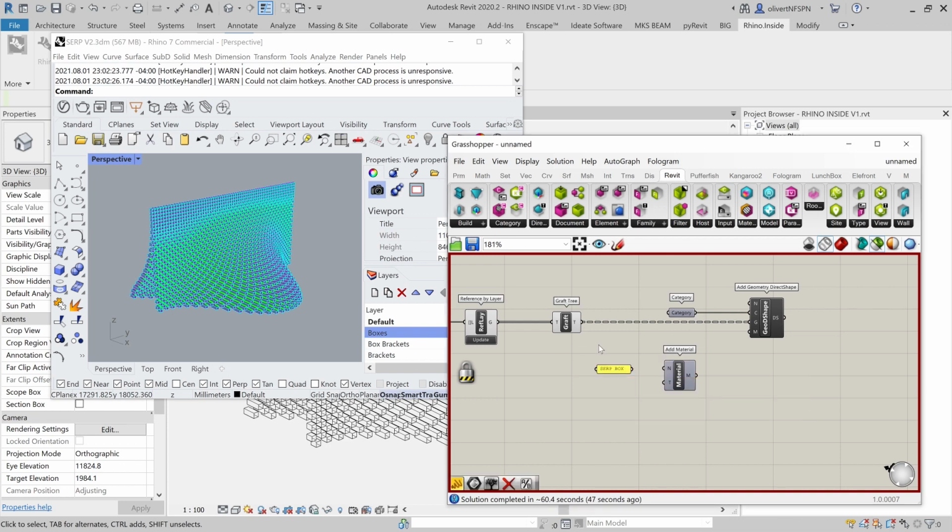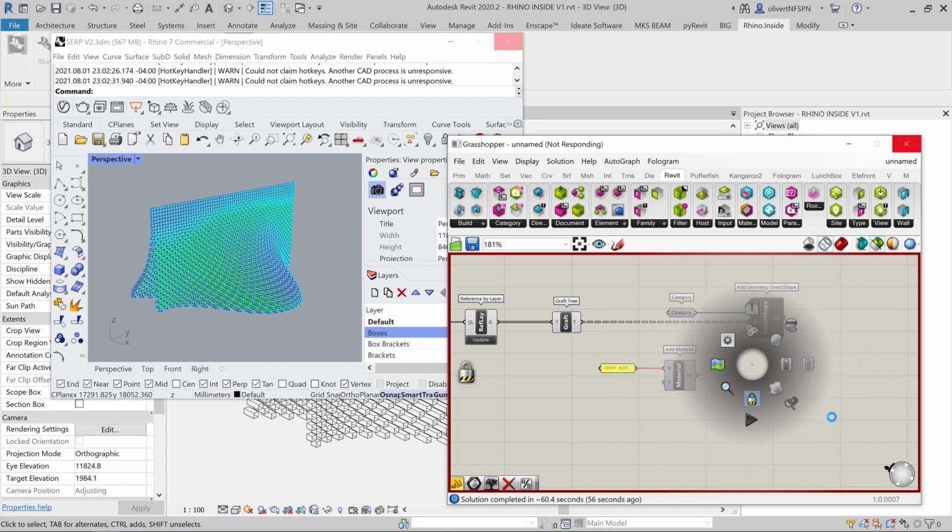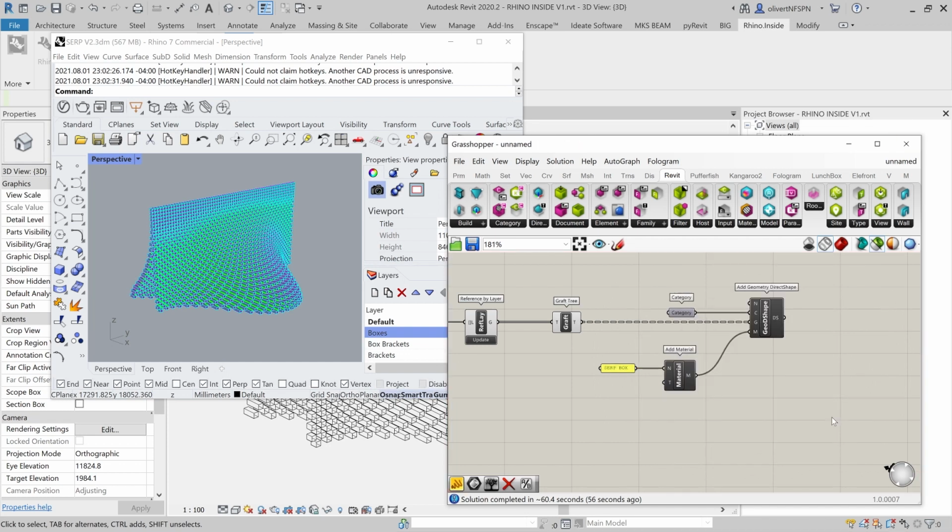Right, and it's going to create a material in Revit that will be assigned to this geometry. And again, that's just a nice way that I can control graphically how these look. I can make them slightly gray or apply a material to them through Revit, allowing us to get into our more typical Revit workflows. So there you go.